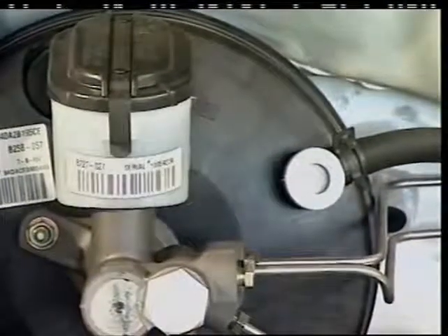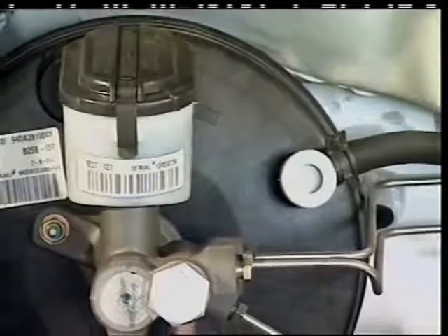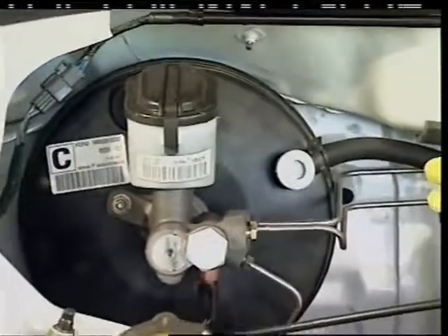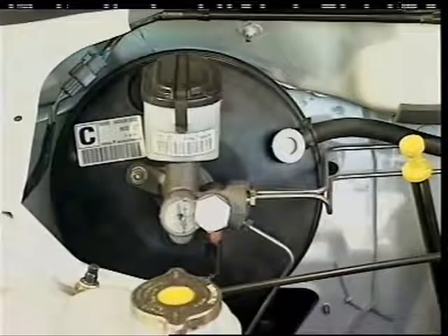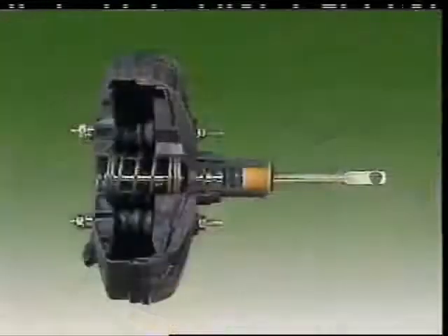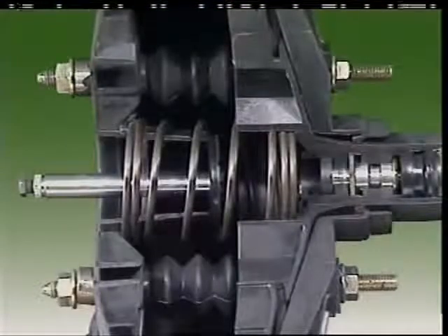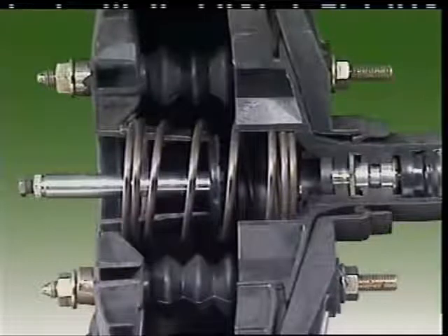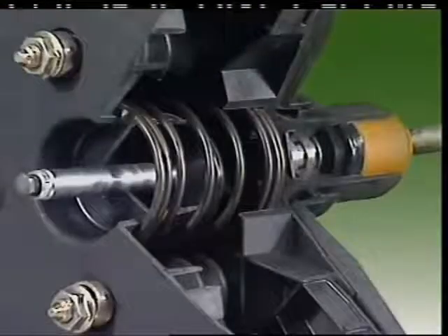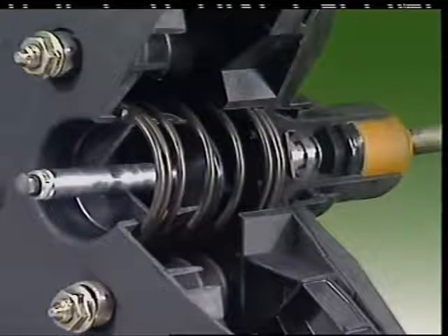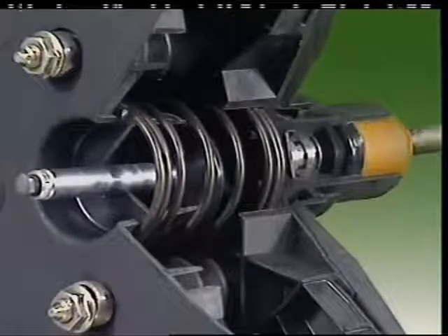A hose connects the intake manifold to a vacuum check valve on the power unit. With the engine running, the vacuum in the intake manifold is used to evacuate the power unit. This valve is held off its seat and a vacuum is produced in both chambers of the unit. The chambers are separated by a flexible rubber diaphragm attached to the diaphragm plate. It is held in the off position by a diaphragm return spring. The master cylinder pushrod and the control valve assembly are centrally located on each side of the plate.